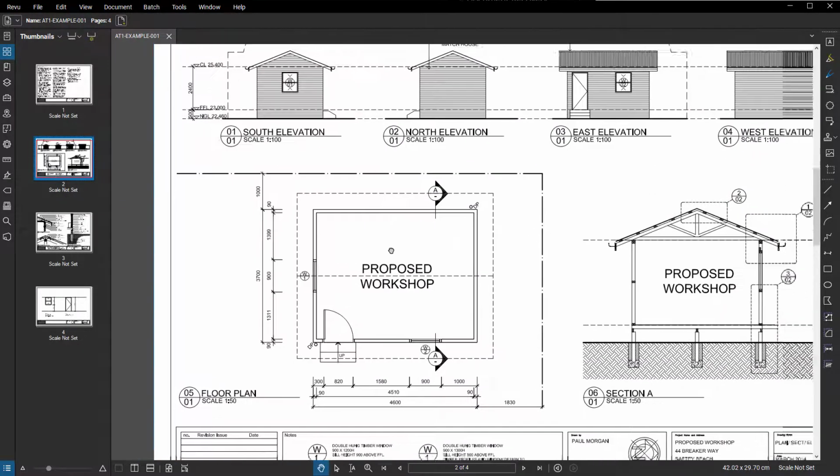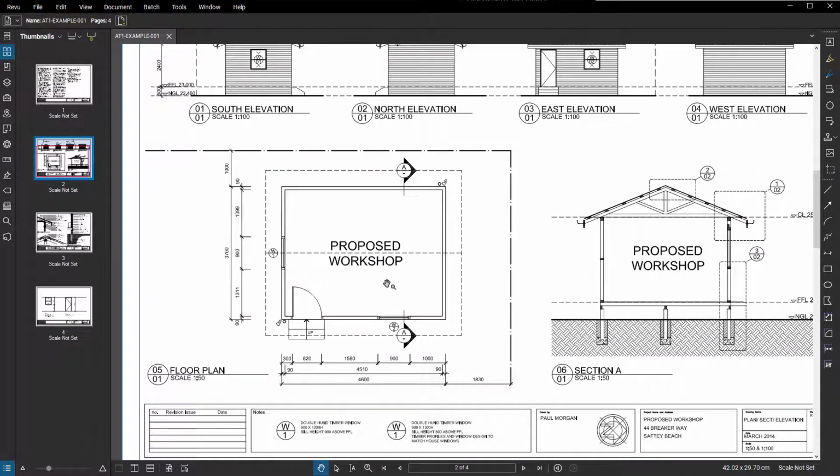And so what we're going to start with today, we're actually going to start on sheet 2, and in particular the floor plan, and just get our basis going there. So we're going to cover guidelines, how to create guidelines, sketch guides. We'll then draw the walls using the polyline system that we went through in our introduction last week. We'll then draw the roof dash, which is this dash line here, which denotes the overhang of the roof. And then we'll draw the windows and the doors, and we'll do this on the correct layers.